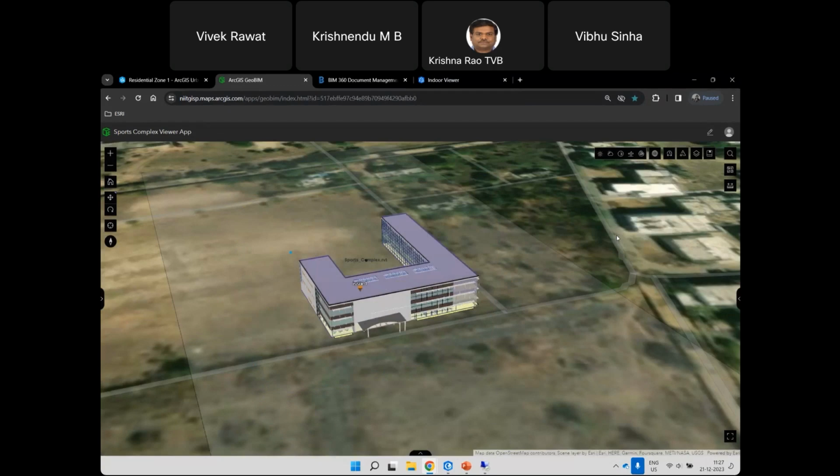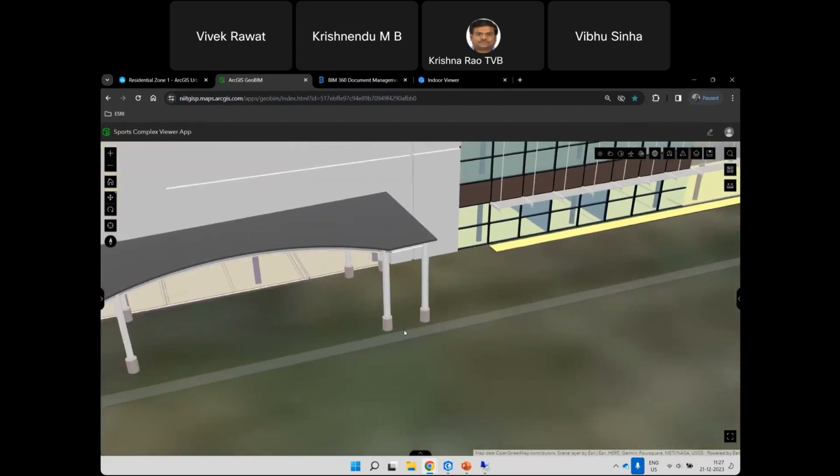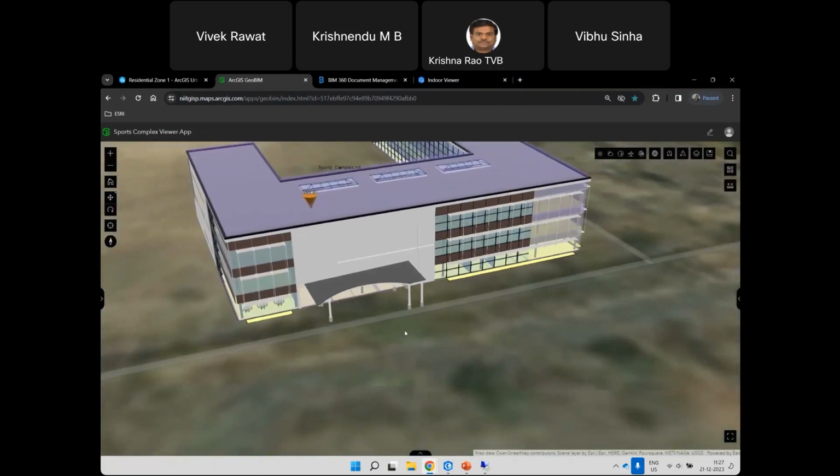As we are aware, in this engineering work we have things like the issue dashboard view, where we raise issues in the construction before doing the work itself. We can do this from the GIS context also, because when we place the model at the exact lat long, some issues come into the picture. If you zoom to this area, we can see the setback taken for this construction. It is not that great. It is very near to the road. That is an issue which I found when I placed this BIM model in the GIS context.